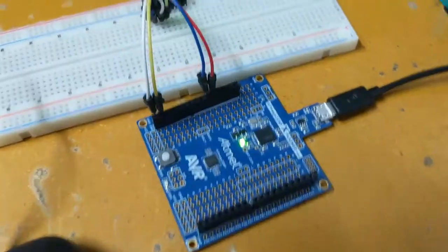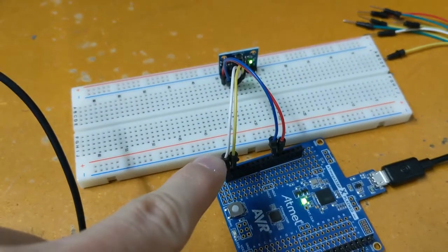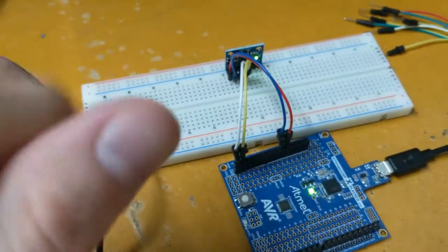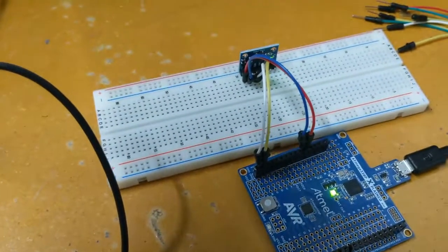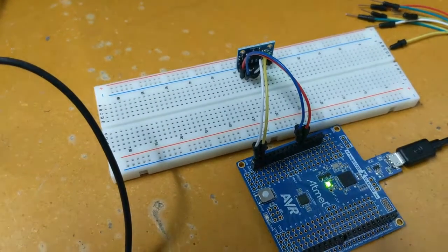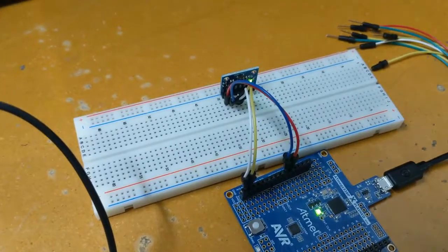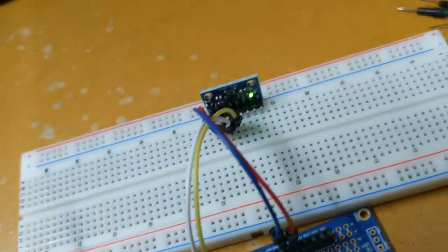So this is the board. Look at that, and it's really easy, right? We have these two I2C lines: the signal clock, and then the actual data line. Normally you'd have to set this up and put two 10K resistors across both of these, held high, as a part of that input, so you actually get the signal to come out clearly. But in this case, the development board actually contains those internally.